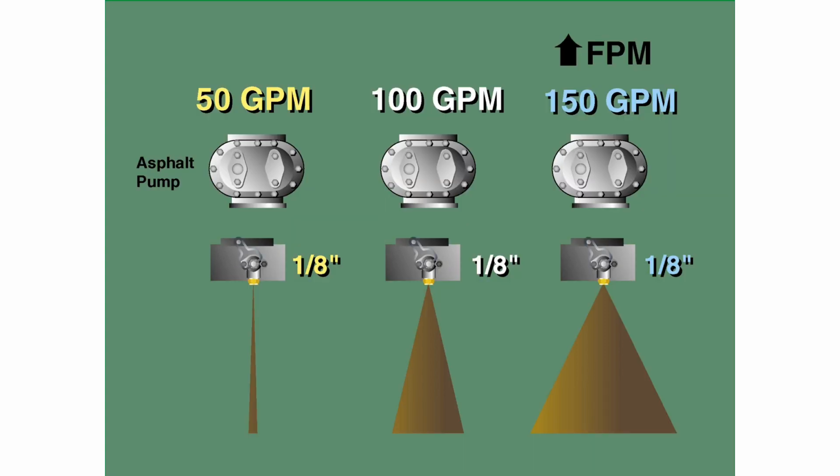The opposite of that is I left my nozzle alone. Again, I have the right application rate here, but it's not fanning out the way that I want it. So what did I do? I had to speed up so that my volume of oil out of my pump sped up also to create the pressure that I needed. Okay, so you have to do it either with speed or nozzle size to obtain the actual spray pattern that you're looking for.